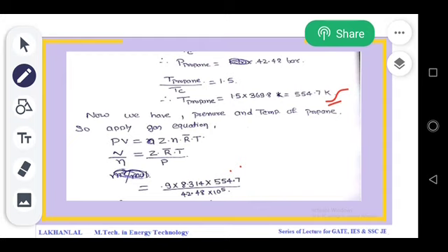So can we apply the gas equation here? But we cannot apply the ideal gas equation here because it is given that the methane has a compressibility of 0.9, and since both the gas propane and methane are at same reduced pressure and temperature, they are going to have same compressibility factor Z, which is equal to 0.9.